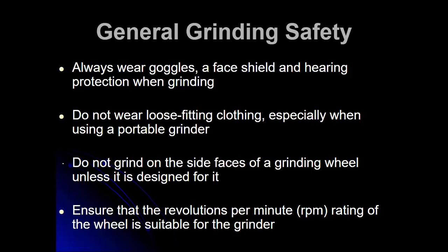You do not either. Around these tools, though, we're not wearing loose-fitting clothing, especially when using a portable grinder. There are many, many, many instances on the internet where people have got loose clothing caught in a grinder, and it's not good.